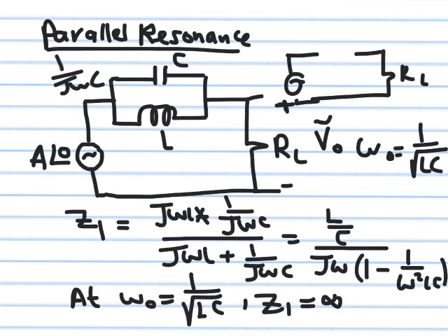Okay, what happens at very high frequency? At very high frequency, 1 over j omega C becomes very small. Effectively, if omega is infinite, this becomes 0. So again, this looks like a short circuit. The inductor will behave like an open circuit because its impedance is j omega L, and if omega is infinite, this becomes j infinity. So effectively at very high frequency, this is a short circuit, and then the output will follow the input. So you could see at very low frequency, the output follows the input. At very high frequency, the output follows the input.